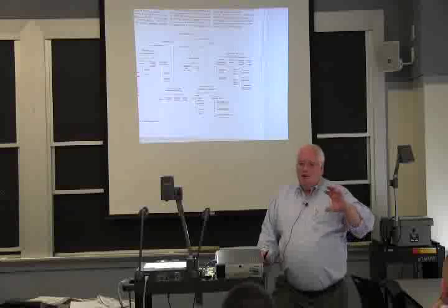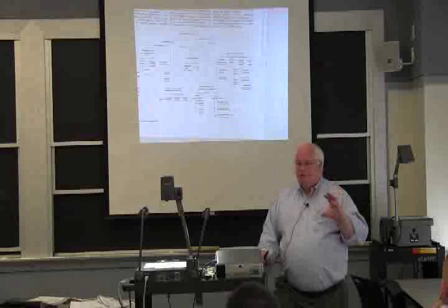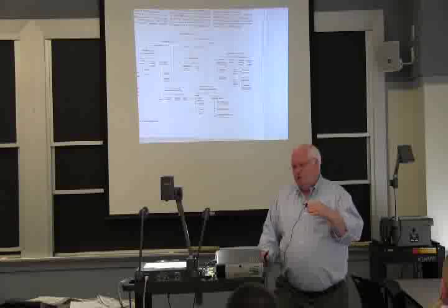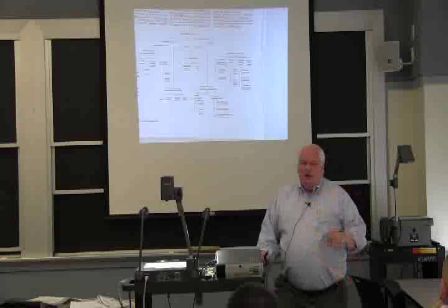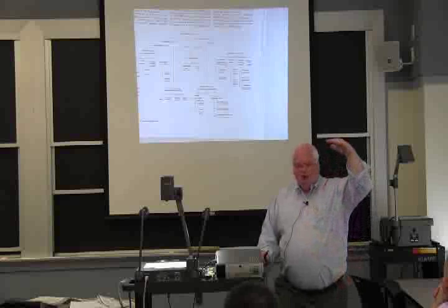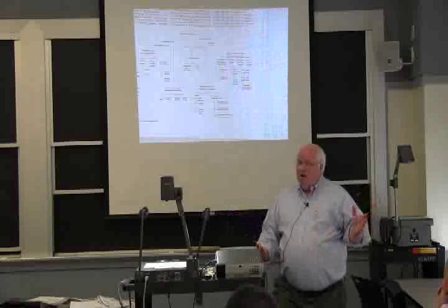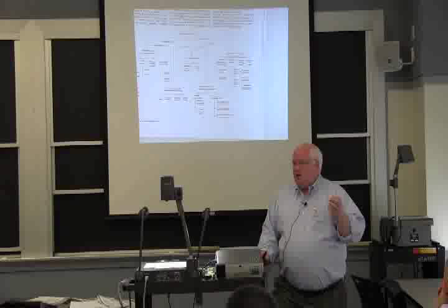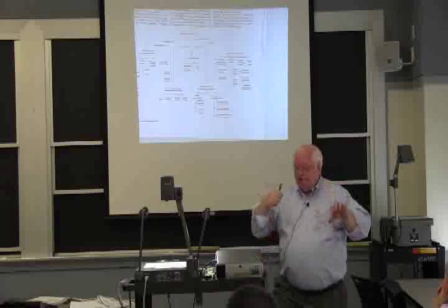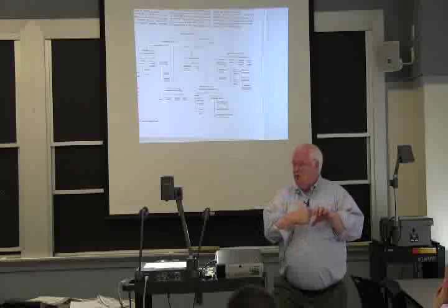And at that point, they basically changed the experiment, and a year later he ended up with what's called rheocasting, for rheology. Rheology is a study of fluids, and essentially they would cool the liquid down and stir it, just like you make soft serve ice cream. They were doing this on lead tin alloys, but they showed they could get unique structures, and they've already extracted half the heat of fusion. And so they thought this would be great for die casting, where you inject the metal into a solid mold, you just push it in under pressure.